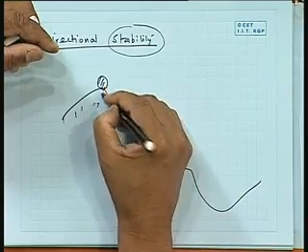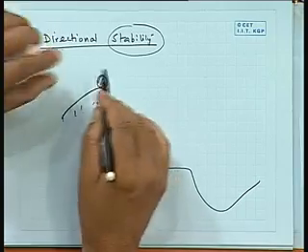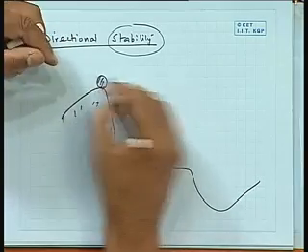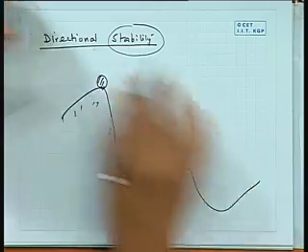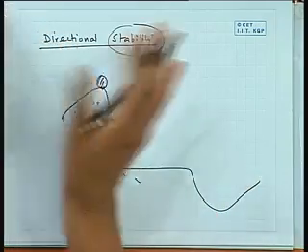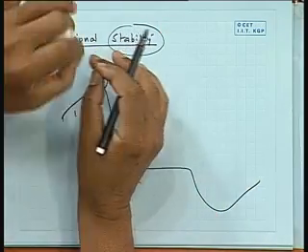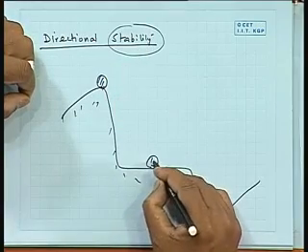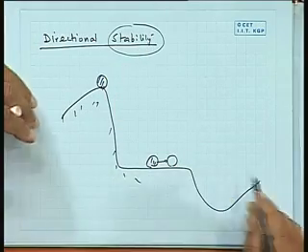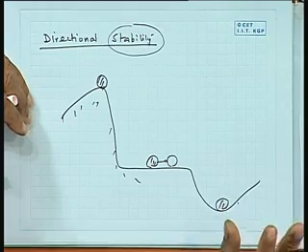This is obviously unstable, because this is the equilibrium position, there is no force, but the moment you change it, it is going to go away from that. So, it is unstable, it is deviating. If you give a momentary disturbance, it deviates from its state of equilibrium. You keep that here, it is neutrally stable, because you shift it here, it stays there, and here this is stable. Similarly, for a ship, you would expect that it is going on a straight line, maintaining a direction. Now, you give a disturbance, so it has changed its heading. Should it come back to the same straight line, or should it keep deviating? That would be the concept of directional stability.